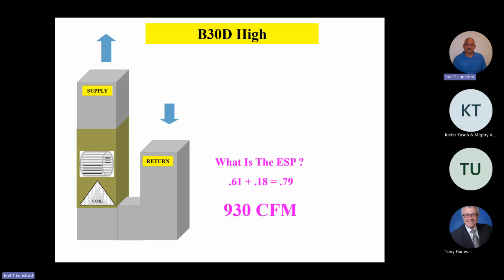Now on a variable speed air handler, an ECM air handler, the other thing you'd also notice is the fan is really ramped up, especially on variable speed, really trying to move that air. So the moral of the story on that good question is: before you do any static pressure readings, make sure you've got a clean coil, make sure you've got as much air moving through the system as you can, and make absolutely certain that you've got a clean filter for these tests. That was a good segue into making sure your coils are clean before you do all this stuff.